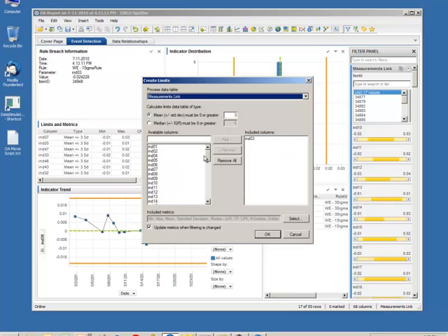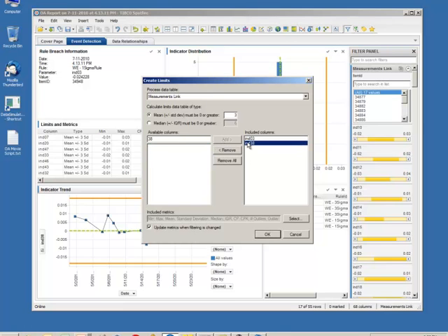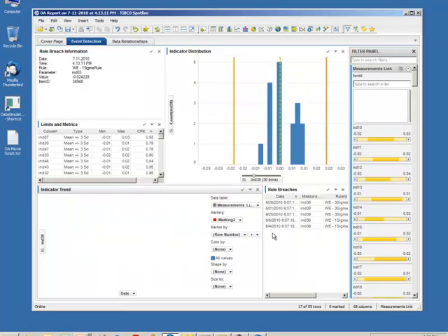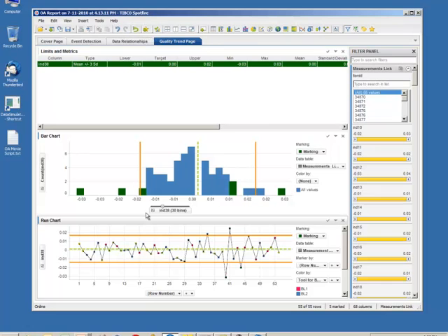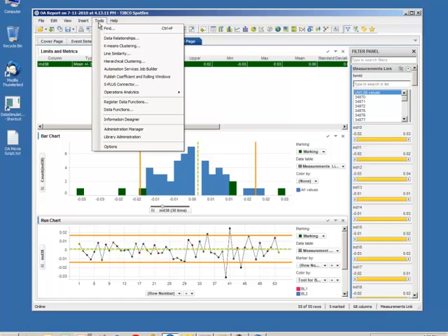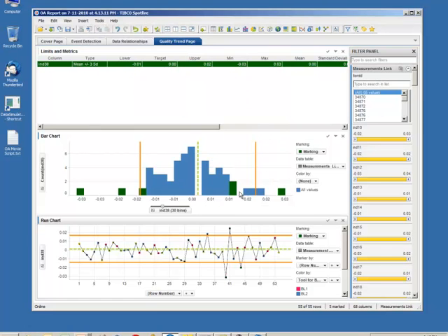So we'll go back to Create Limits, type in number 38 here, pick that variable, I'll remove indicator number 3, and make the calculation. Here we are, back to the particular indicator, and you can see that I've tightened up the process windows a bit. If I reset all the variables, you'll see that indeed this process window is now a bit tighter. And we'll go ahead and publish that out into the event system. And there we go. One limit publication has been acknowledged by the system.